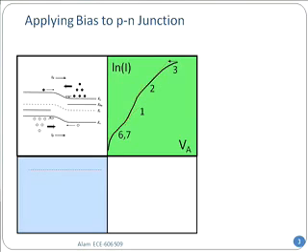in the forward bias, let me just suggest that although it's a logarithmic increase in the current, you will see that it is not a simple logarithmic curve. Had it been a simple logarithmic curve, then log I would have increased with the applied voltage as a simple straight line. But you can see that there are curves, twists and turns that I have labeled as 1, 2, 3, and 6 and 7, these various regions. These various regions are very interesting. They contain within them a lot of physics that as graduate students we need to know.